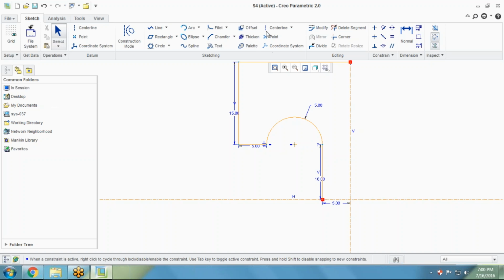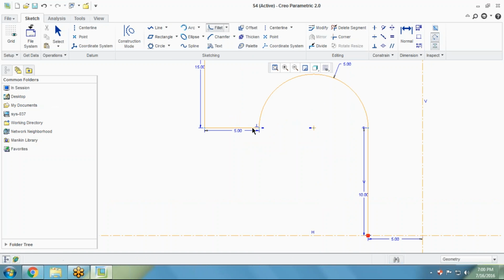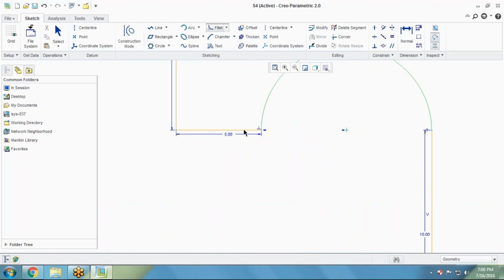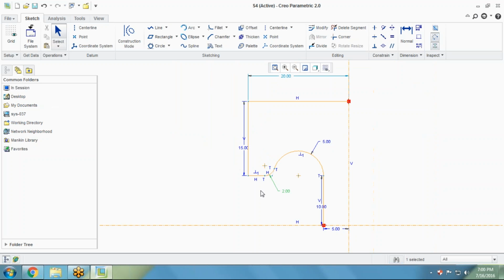And now after that we are just creating one fillet operation, and now picking this arc, and second one will be line, and it shows me the dimension, but it showed me the warning also that the dimension has been specified. That's why now the dimension has been deleted. Now we are specifying the value is around 2 millimeter. So we'll see there this is a starting point going through this way, and now this is the end point.